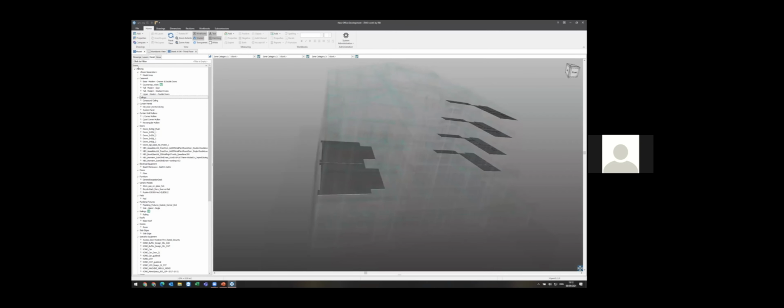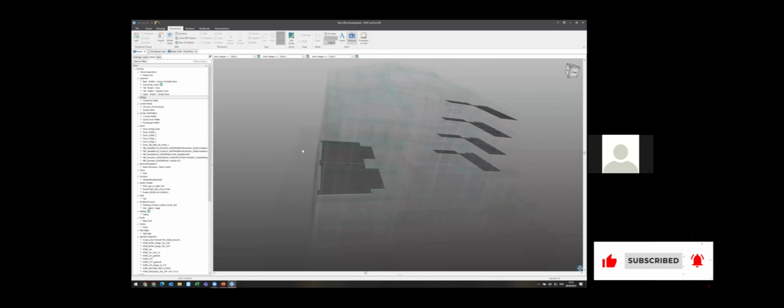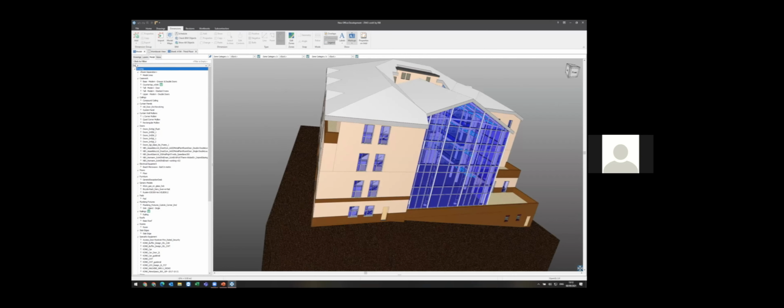If I want to, you can measure manually. So into my dimensions ribbon, I can switch into point mode, and I can click around the 4 corners of an object, or more corners in this case, and do just some manual checks on the geometry of the objects, and I can check whether the geometry matches up with the properties. But once you've satisfied yourself that the properties are accurate, you can then move on to automated takeoff approaches.